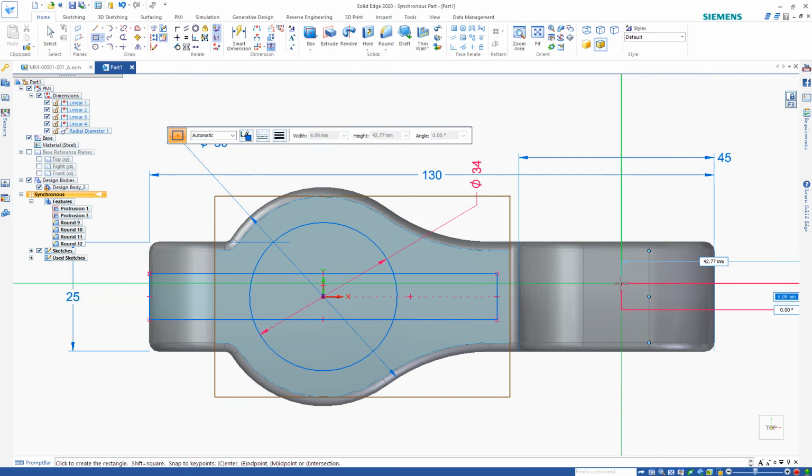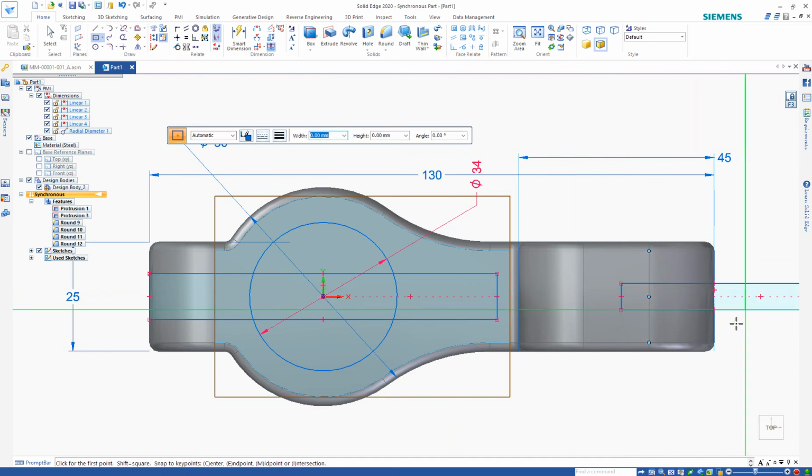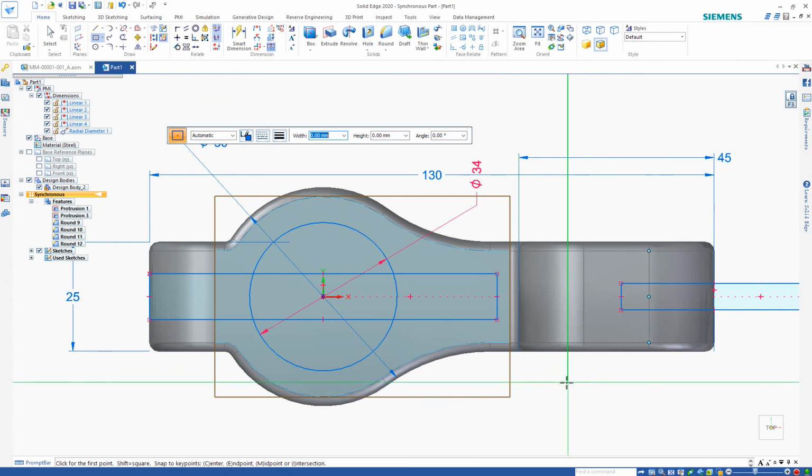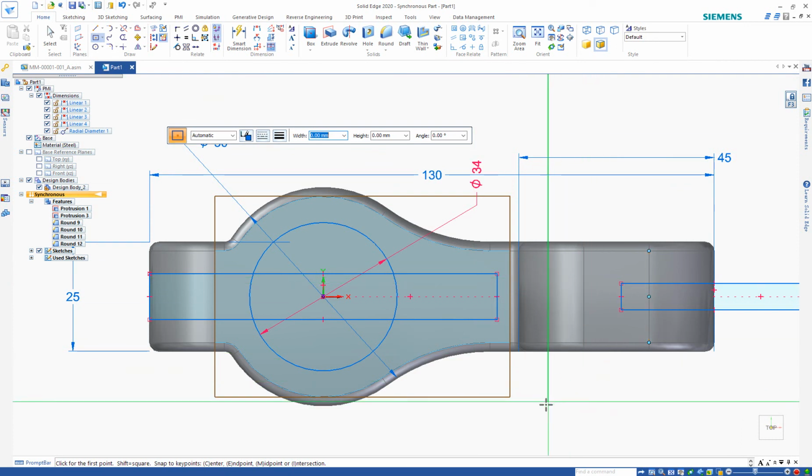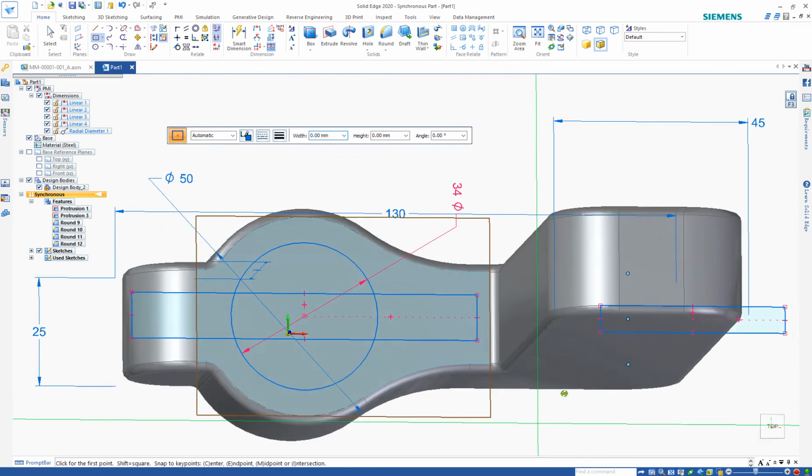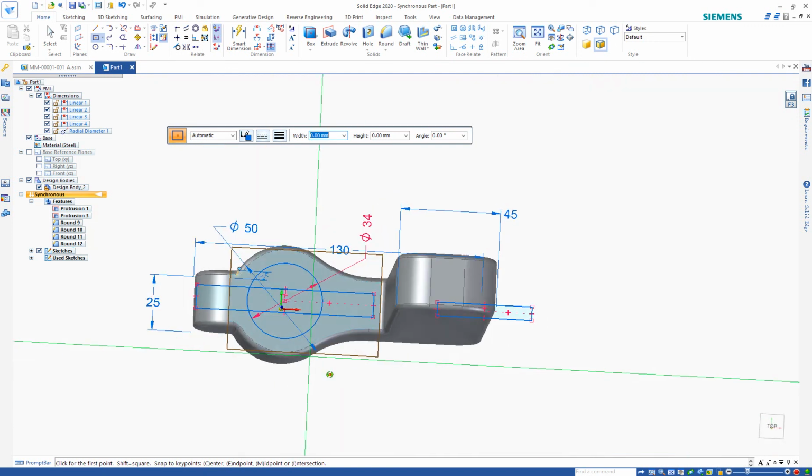So if I wanted these 2 slots to be the same width, you don't really need to add sketch relationships at this level. You can leave it different at the sketch level, and then when we build it up, you can use different face relationships to make them coplanar or things like that later. So far we can go with this sketch.